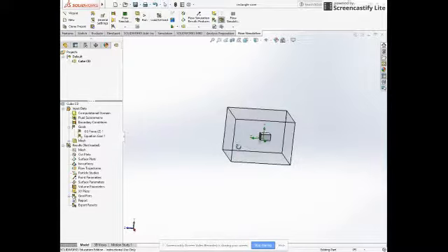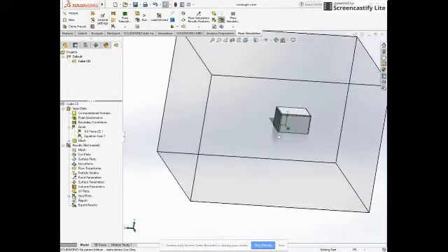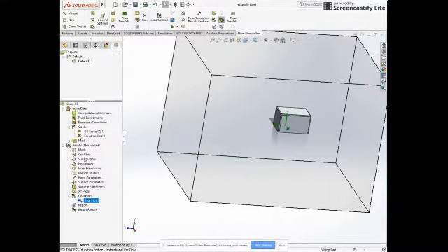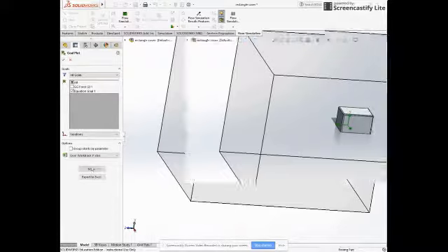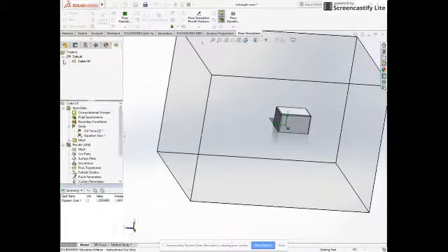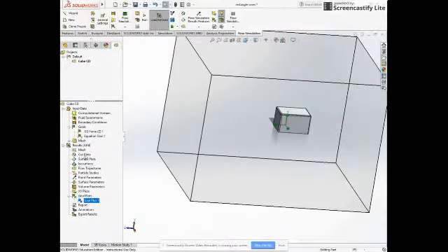We will go ahead and go over to another analysis we performed on just a standard cube to show the differences in the drag force. Here we're going to open the same equation goal. This is going to show us the drag force once we load the results here. Going to take a look at that. And here we can see a coefficient of drag. It comes out to be about 1.25 after it's converged.